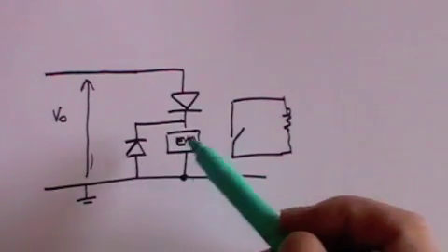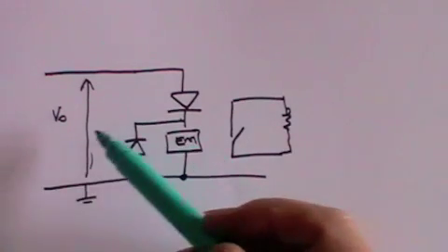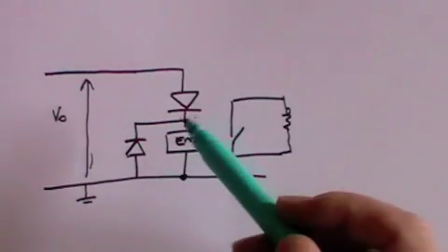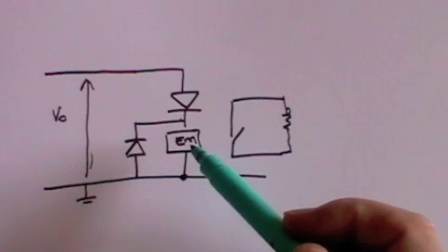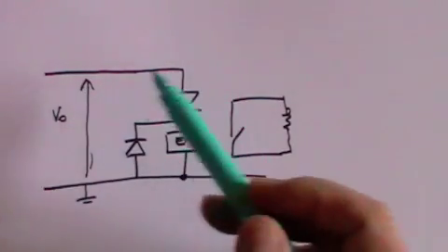What's the reason for that diode? Well, when it gets light again the following morning, this voltage is going to flip to become negative again and the current will stop flowing. The electromagnet will stop, but there is often what's called a back EMF, which can damage the circuitry.